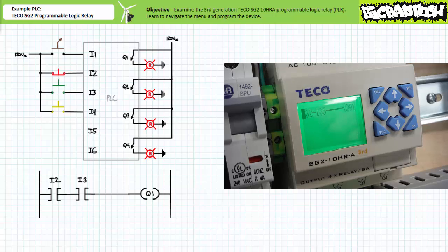When only the green push button is being actuated, the program shows input 2 is allowing logical continuity to input 3, and input 3 is allowing logical continuity to the Q1 output, symbolized by a highlighted bold rung. The output is energized and the pilot lamp comes on. The output, being electromechanical in nature, would exhibit a characteristic audible click when it closes.